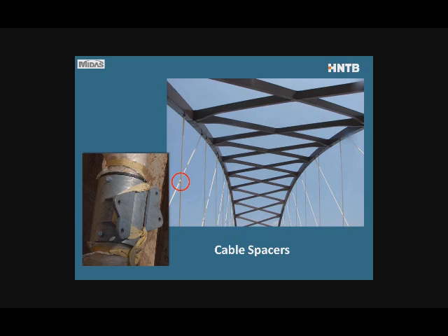The last step is to prevent the cables from slamming against each other where they cross over. So this involves installing of a cable spacer. This is a view of Blennerhassett, and you can see nicely what I showed earlier about the bracings complementing each other, the arch bracing and the hanger bracing. So it's just simple clamps.